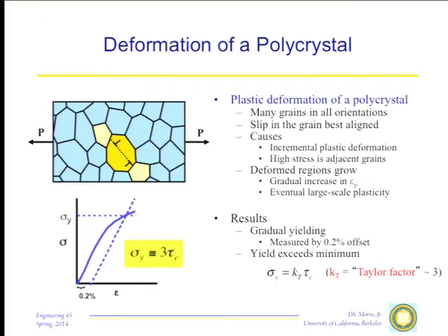Well, that grain begins to deform, but the grains around it haven't deformed yet. If I take one grain and change its shape and it's still attached to the grains around it, I'm going to put stresses into those grains. So the fact that this grain deforms stresses the grains around it and promotes their deformation.